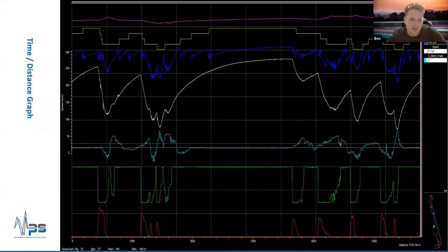Likewise, if there's a big difference in driving line, one driver could travel a further distance than another. So you have to take the apex points and the braking points with a pinch of salt if your drivers are massively different. But in most cases, I find a driver will quickly settle into driving the same line, and therefore you can trust the distance measurement.